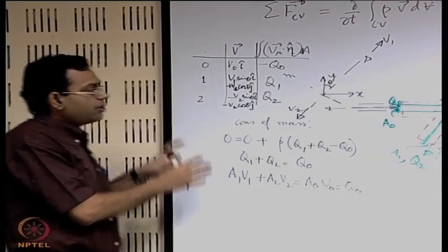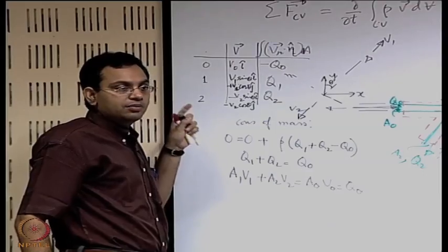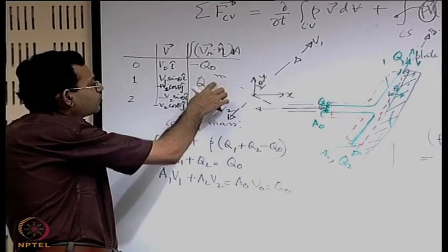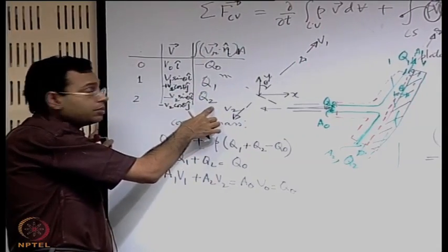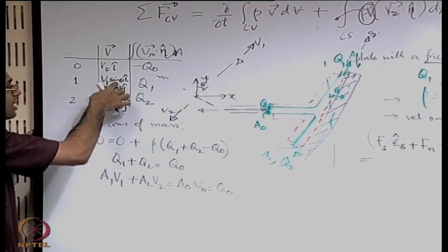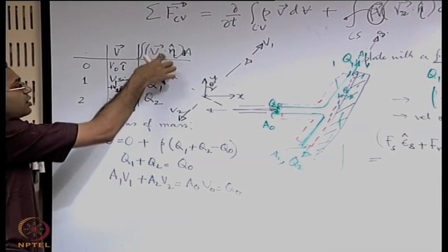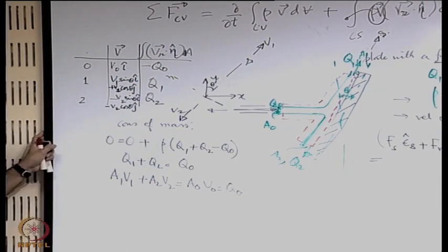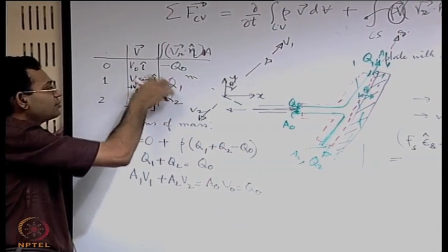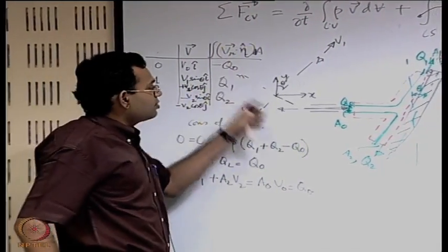See, this is very straightforward, but I want to emphasize this because this is a place where students make mistakes many times. By default, it is common to think the outflow boundary gives rise to a positive flow rate, but the velocity that comes with it has nothing to do with the flow rate. So you have to write it in proper vector sense. This plus or minus term has no conflict with the flow rate term, so keep that in mind. Otherwise, just by inertia of writing, you might write this in a similar sense as you have written this. Okay, so let us now substitute that.